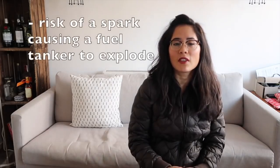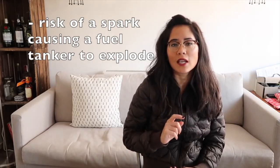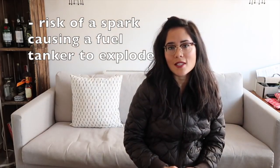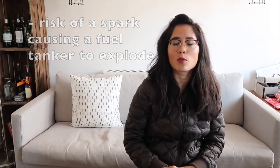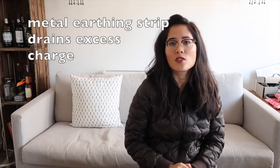They may well ask you, however, about the dangers of static electricity. So that's things like a plane becomes charged when it's flying because of friction between the clouds and the plane. So when it lands and they bring a fuel tanker nice and close in order to refill the plane, you can imagine that a spark could go from the plane to the fuel tanker and cause a massive explosion. So that's a big no-no. So what happens in this instance is the plane is given an earthing strip which is made out of metal, because then that can conduct the excess charge away from the plane to Earth, meaning that there's no risk.